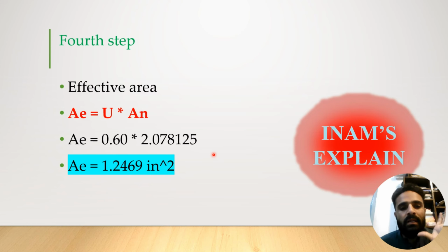So this is the whole lecture on effective area, on how we solve a numerical on effective area. Only two things are required. Number one is the shear lag reduction factor, and the second is the net area. So I hope you got it.